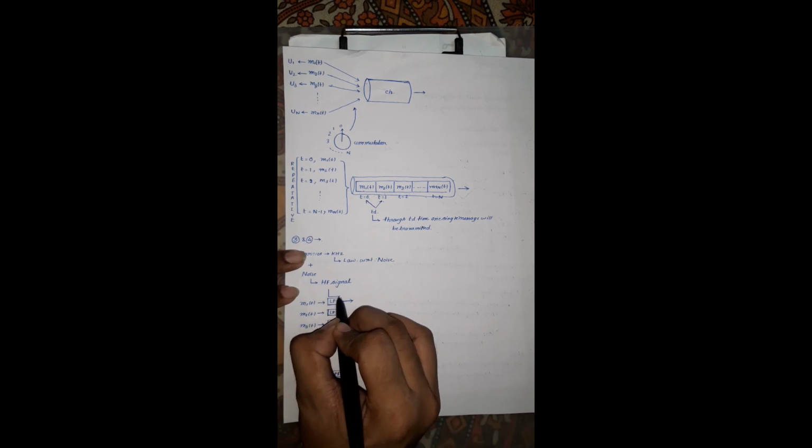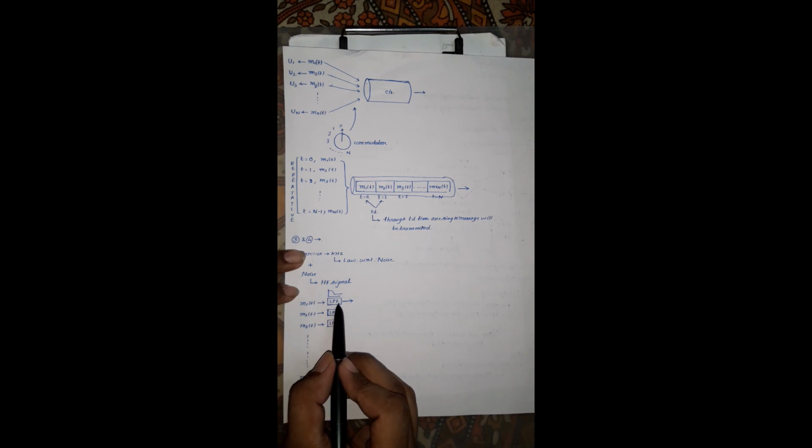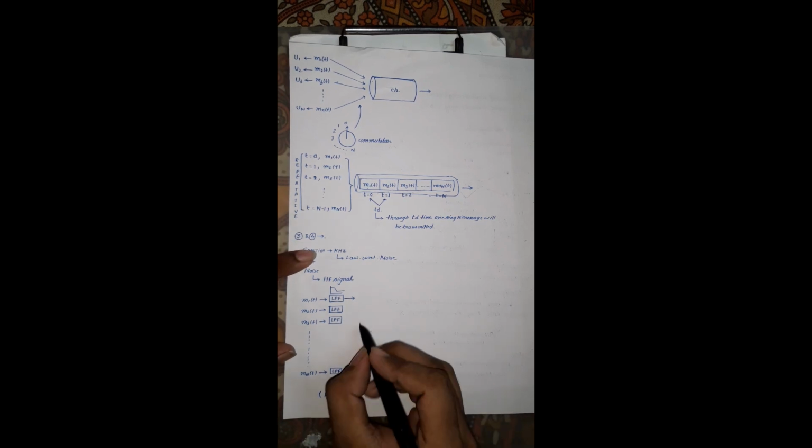What is the low pass filter going to do? The characteristic of the low pass filter is just like this. It allows the lower frequencies and blocks the higher frequencies. That means if the noises are attached, these noises will be removed. So the original low frequency signal, without noise, the pure signal, will be fed to the channel. Then after that, what is the circuit present over here?